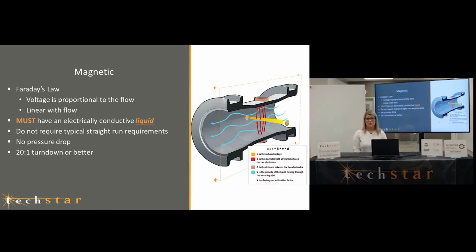So these are great for water, brine flows, anything that is conductive. What it's not good for are hydrocarbons. You can't use them for that, and you can't use them for gases.